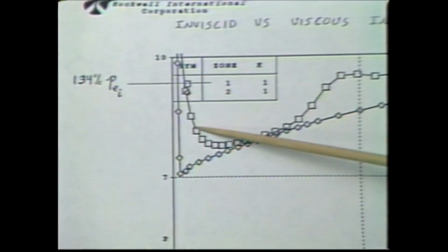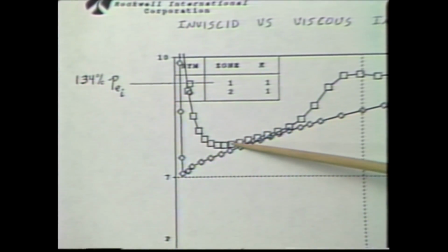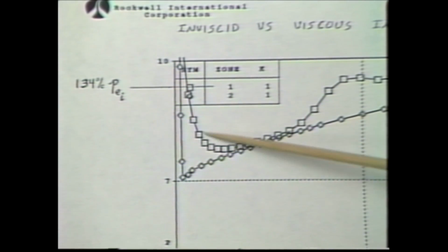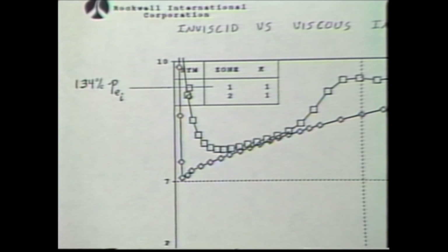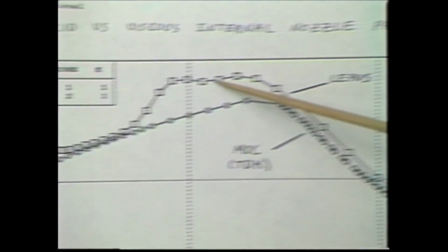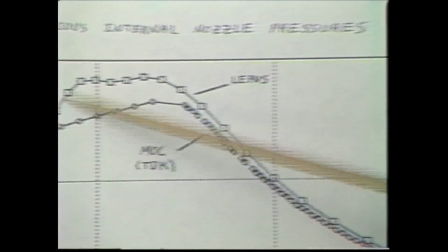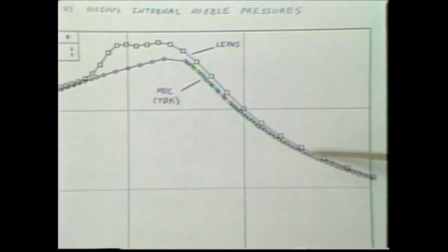Now, it appears that the boundary layer growth was not able to keep up with it, and it actually squashed the boundary layer down. The free stream flow had to turn back again to be parallel to the wall, but then as the boundary layer growth does pick up, that interaction and that pressure increase redevelops and then sort of continues down the nozzle.